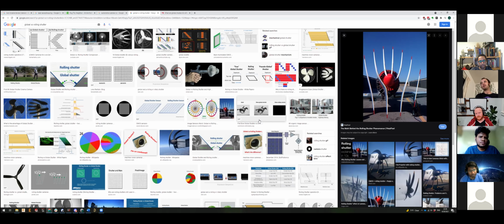You want to run your inference on the 360-degree perception of the vehicle and not individual disparate images, which then are getting potentially stitched together. Because it'd be like, I saw half of a car, I think, and then the other camera says, oh, I also think I saw half of a car. That would be a way easier question to answer if you just could fuse it together, feed your pipeline, and then just look at the whole freaking car. So this notion of distributed compute versus centralized compute, that really becomes pretty obvious what you have to do there.